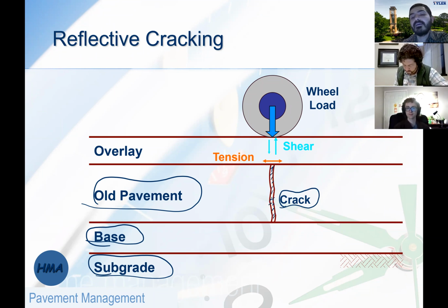And then one of the solutions, which is again one of the easy solutions but not that effective, is just to ignore the crack, or you say, you know what, I'm just gonna have an overlay. Let's have somewhere between 2 to 4 inches of overlay, and cracks are going to be hidden, problems are going to be solved, and we're done. That is a big mistake. It's just an illusion that's going to last maybe 6 months or a year at the most.